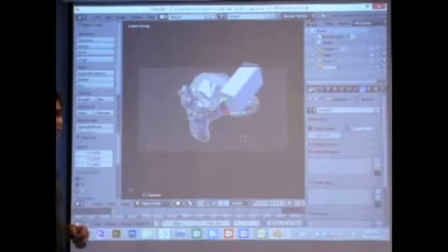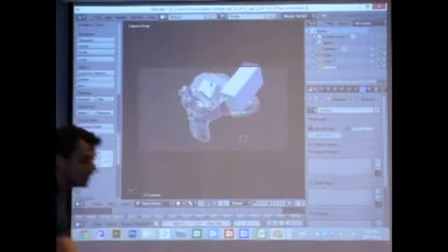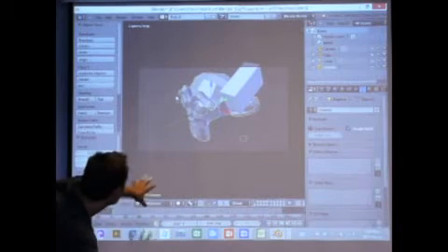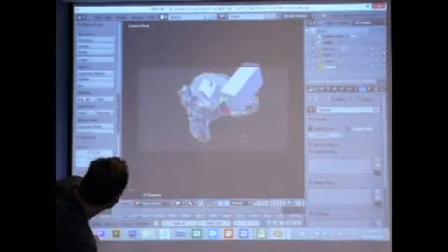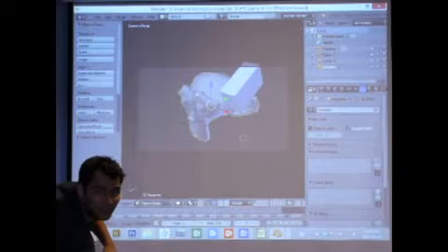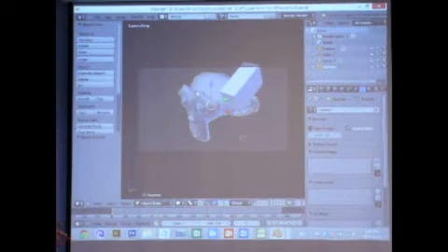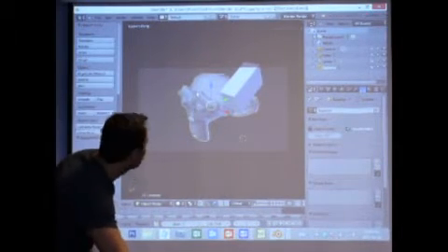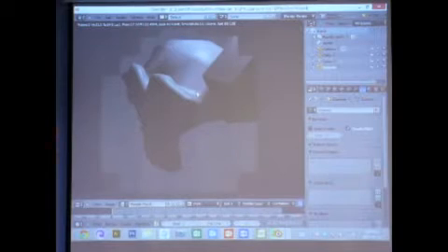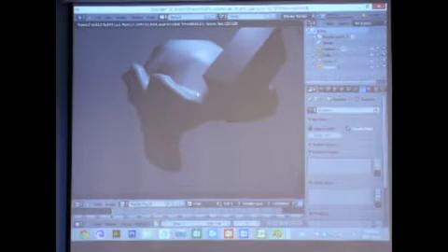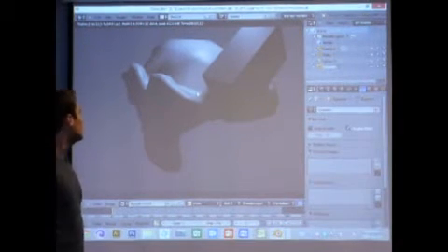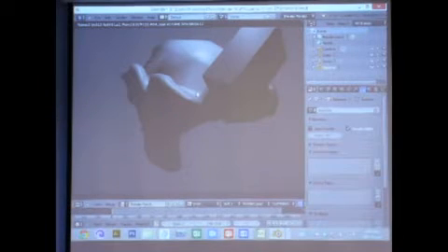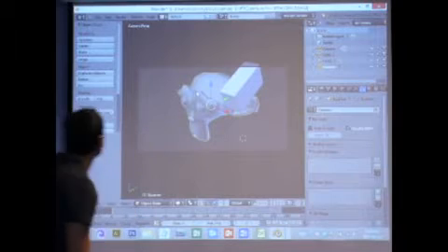Okay, let's make this monkey head look much better. It's really jagged right now. It doesn't look nice. If you click on it and press smooth, right away you get something that looks much better. And you can press F12 to render it to get this nice shape. There. The lighting's a little off. So smooth is just on the left side, right here.